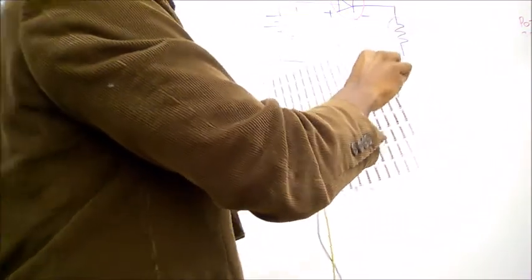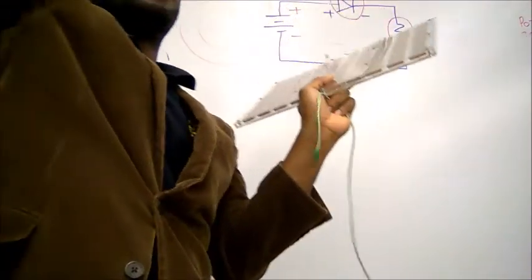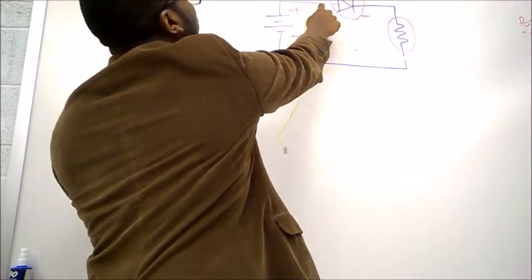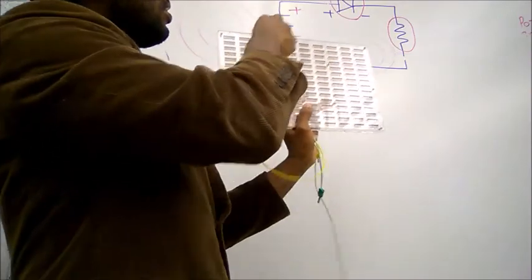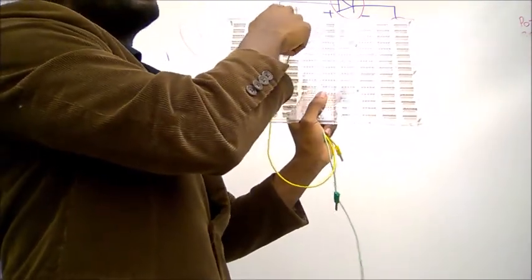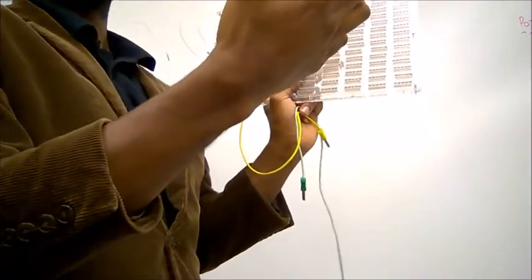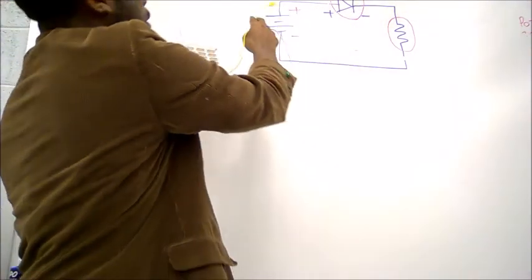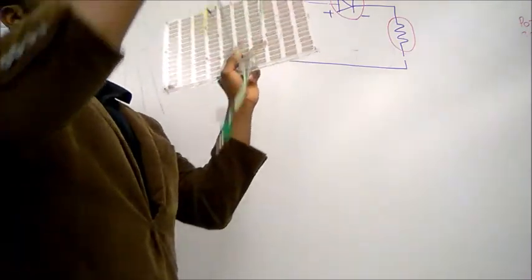So if you look at our circuit here, we have our power supply positive. Now, if this is coming from my power supply, this is the positive from my power supply, and I want to connect it to the leg of the LED. I simply have to put it in the same row with it, because then it's going to be connected to it, right? Because the material behind this is conductive, so it's going to make a connection. Likewise, and again, this does not go to a battery, but this represents our power supply. So this positive goes to our power supply, correct?